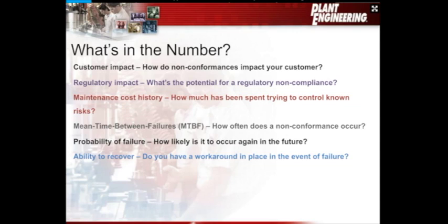So the criticality analysis had to identify the fact that that conveyor had no workaround. It was a single point failure that would stop the process. So we also wanted to look and make sure that recovery means or procedures were a way to validate significance of the asset.